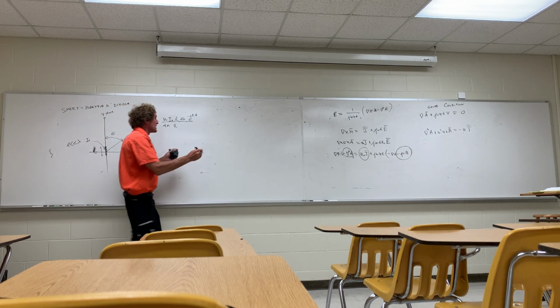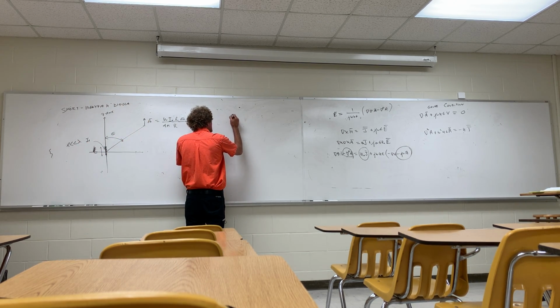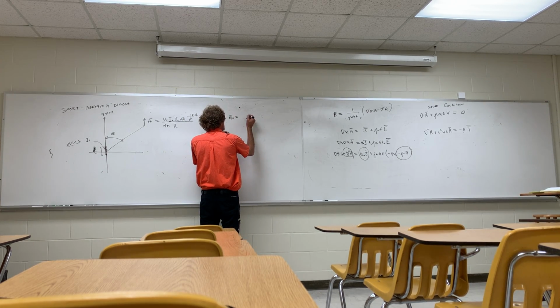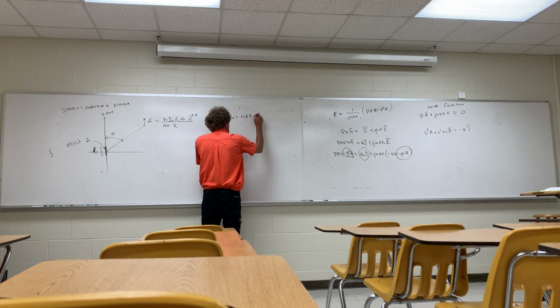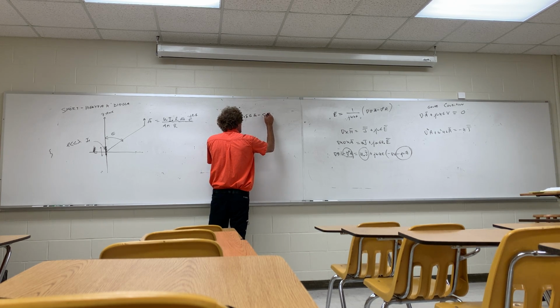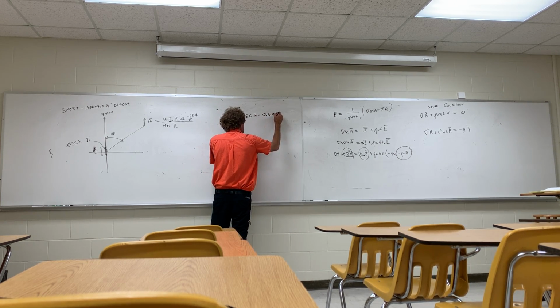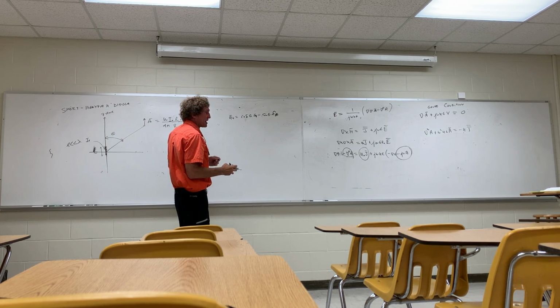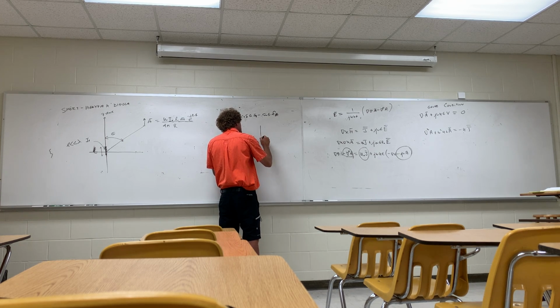Now I get down to this point, and in Wentworth's book, he's going to say what we're going to do is make AZ go to cylindrical or spherical coordinates. AZ itself is going to be cosine of theta AR minus the sine of theta A theta, and this is just a standard transform to go from Cartesian or cylindrical system to spherical. And here's the real deal. If this is the AZ, a unit vector in the AZ direction, and this is the angle phi,